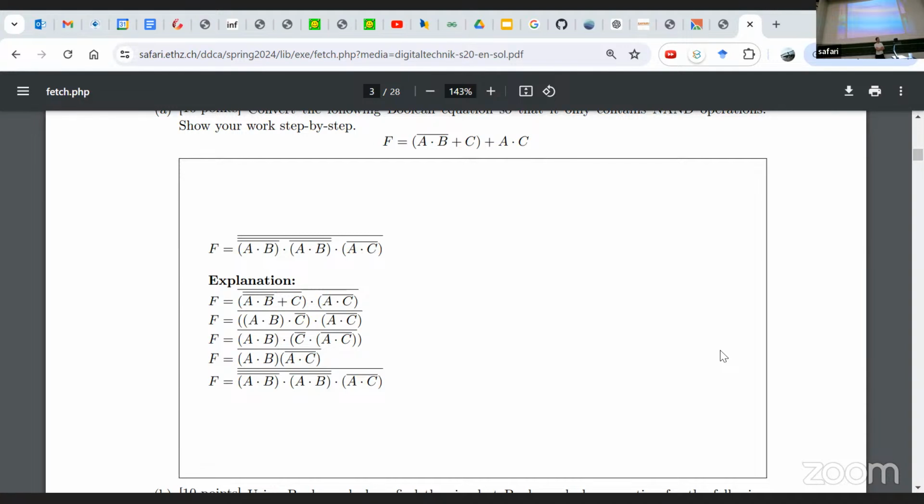And this is the address. And we go to the memory, we are not done, and get the value for S0. And then here we write it into the register file. And so once the clock edge has arrived, the value that is going to be S0 is ready. It's standing right here, saying, I'm here, I'm here, I'm here.